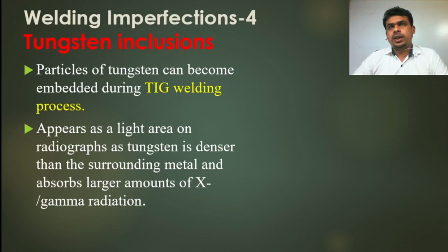When we attend the CCV examination, we see some macros. When you do the macro assessment, you can see the writing at the top side saying which process this macro is for, TIG process or MMA process or FCW process. They must mention the process. What is the reason why they mention the process? Because if it is the MMA process and you see something inside the weld, you need to consider slag inclusion or other things. You cannot consider it as tungsten inclusion.